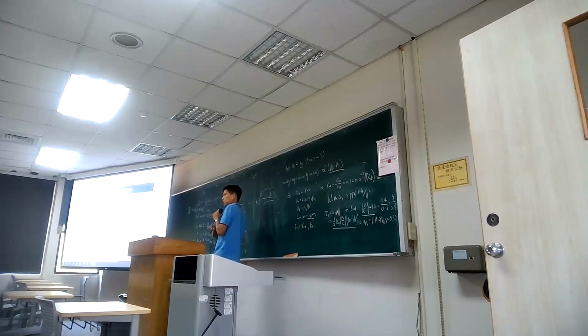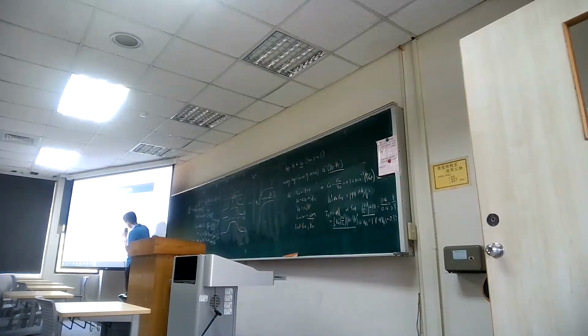And then when you are working with the depleted part, you get a mild carrier, right? Because there is a depletion region, you get a wider depletion region, and you still have the same doping here. If you look at the potential along the gate, you can see the one behind will bend down a lot for both the intrinsic level, conduction band, valence band, and also the Fermi level, which will be the quasi-Fermi level.